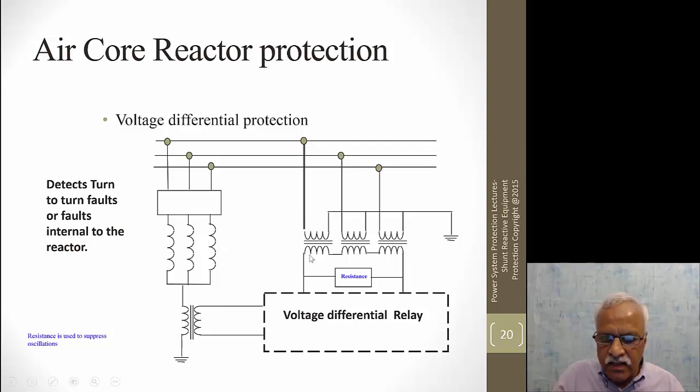We look at the zero sequence voltage on the distribution bus here. It could be 13.8 up to 34.5 kV, with the neutral voltage monitored with another PT here, or a resistor potential device, which is the most cost effective and is used in these applications. This resistance is used just for damping out the oscillations because of the bus capacitance and the system inductance. That is why it is used, but it is out of the scope. I just wanted to mention it here.